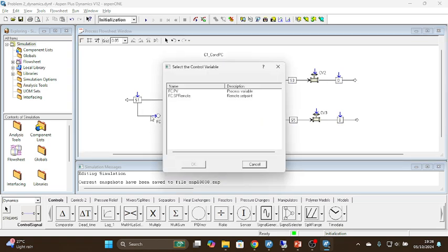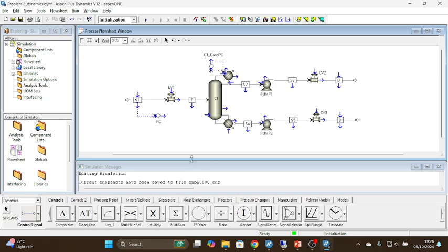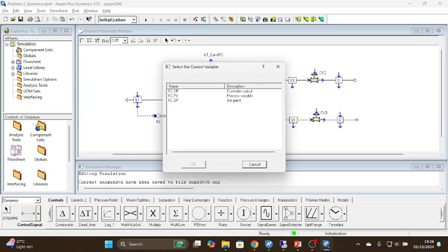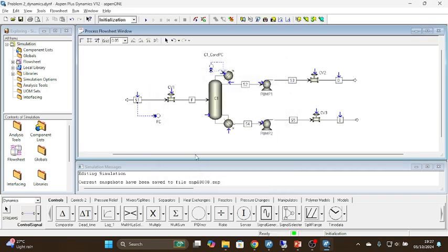It is going to come over here. Over here this is a process variable. We are going to click on OK. Then this output that is coming over here, this is the controller output. We are going to click on OK. This is going to come inside the valve. This is the control valve over here. So what is this flow controller doing? It is going to check the flow rate and then adjust this control valve. Okay. Now our next objective is